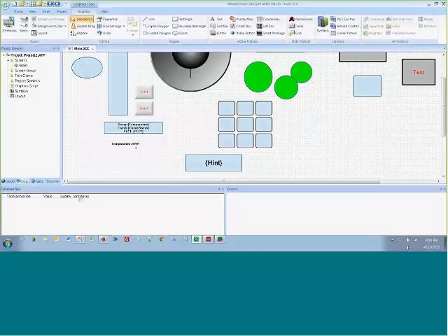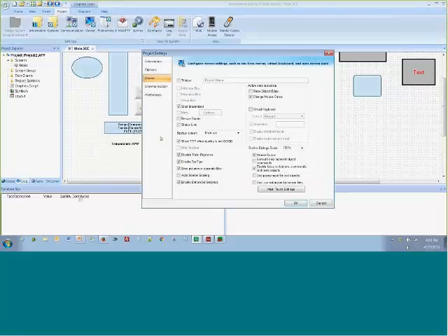If I then want to apply the virtual keyboard, what I need to do is go back into those project settings in the viewer, this virtual keyboard section. So if I check the checkbox there, then I get to choose what is my default keyboard that I pop up. Is it a numeric keypad, an alphanumeric keypad, or an enhanced keypad, which is kind of a smaller version of the alphanumeric? If most of my entries are numeric, then I'm going to choose this keypad to make that my default.